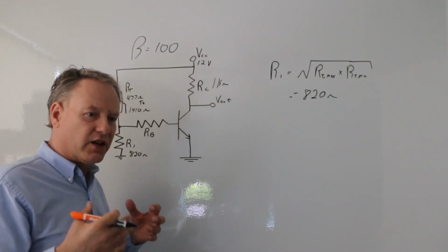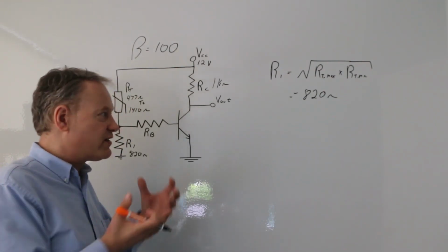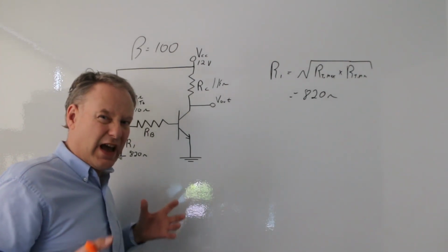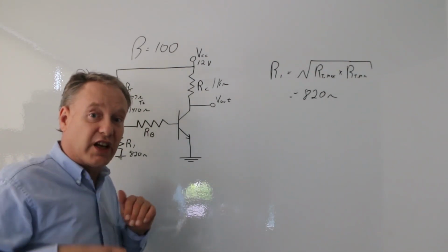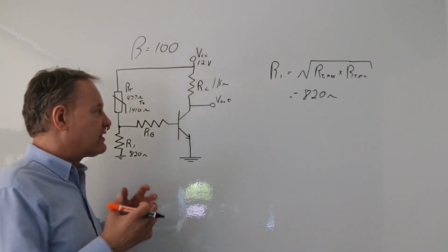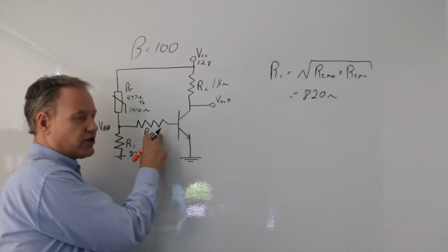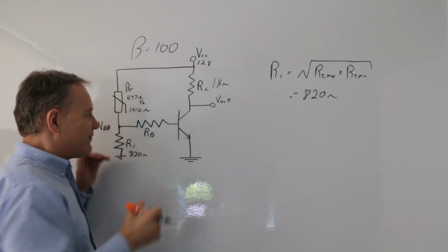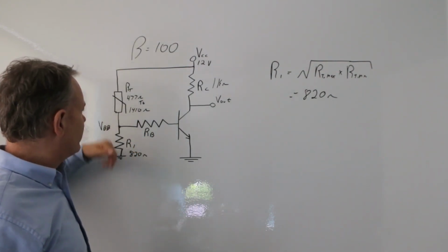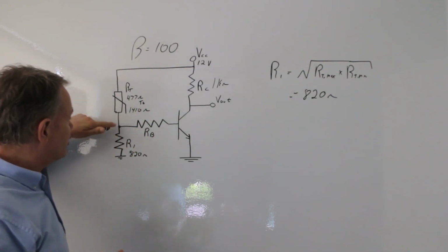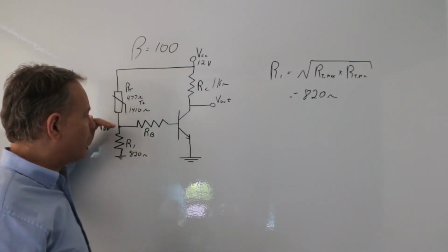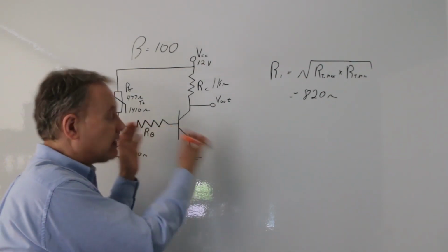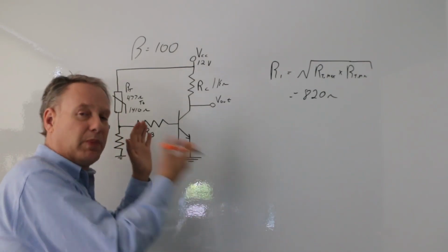I need to calculate some stuff so that this thing fully saturates, and actually it's completely off, it goes into the cutoff range. So I have to design this resistor so that the current coming through here, depending on how the voltage changes here, depending on this resistive change, is going to completely open this or completely close it.